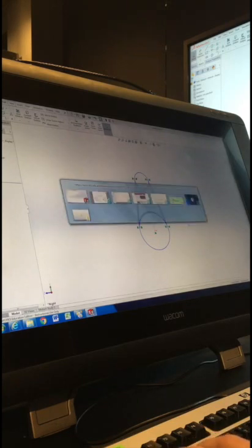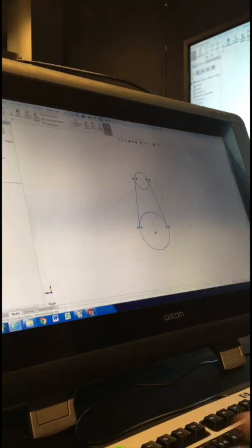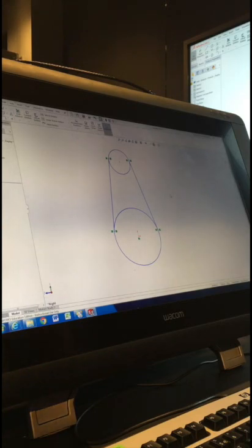If we go back to this sketch here, this gives us our only sense of scale for this part, okay, the A to B, which is the 90 millimeter. All right, so I'm going to show you now how to add dimensions. Dimensions are used really commonly as well, that's the last mouse gesture, where you right click and drag up, and that will give you the Smart Dimension tool.